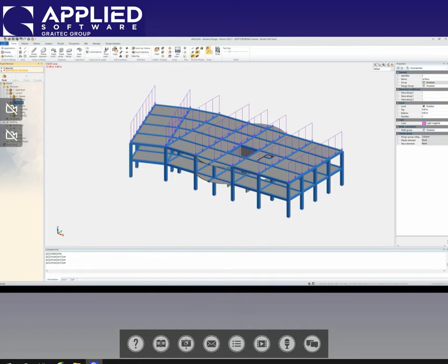From these lists, you can always hide some stuff, you see here, and display them. You can even select some members directly from your structure here. And same thing for the loads. I have all of my loads listed here. So if you want to select a load, you can go there, and all of the loads are listed here. You can also select the loads by just clicking on them. And similar to members, when you select them, the load properties are displayed here. So in Z direction, -2 kilonewton is what we are currently applying to that structure.